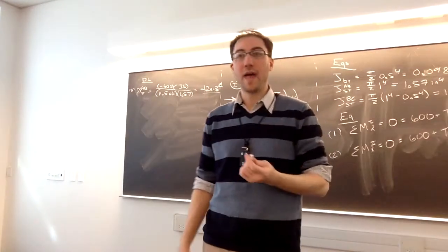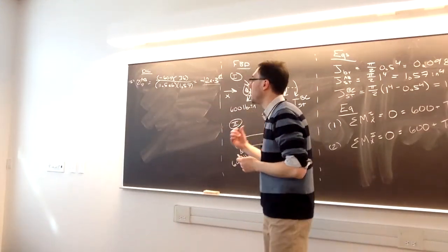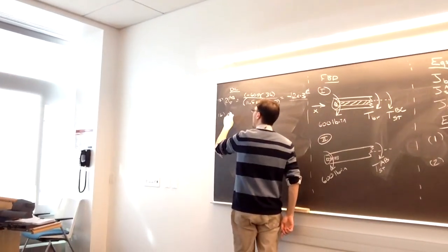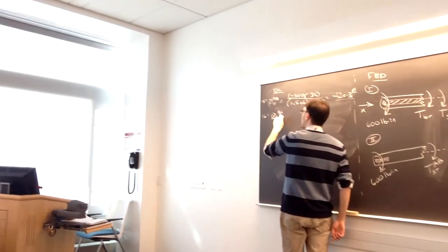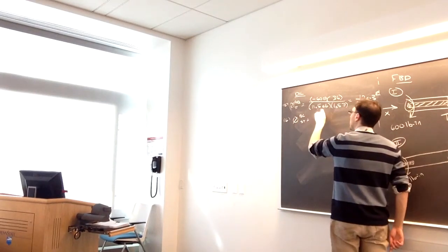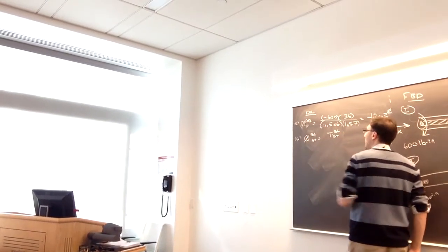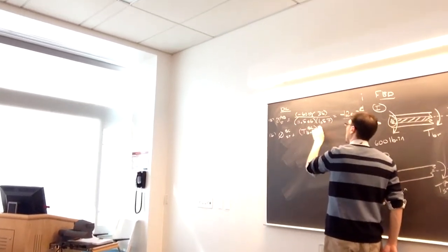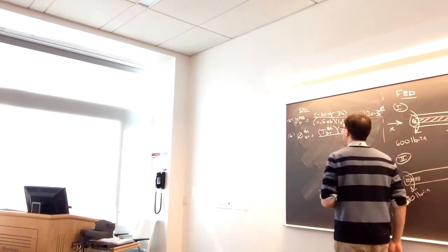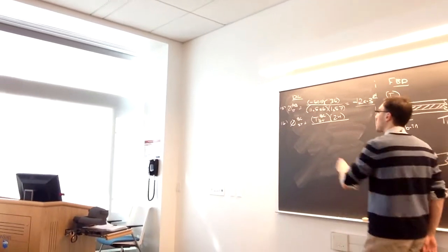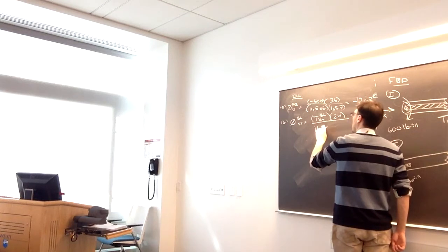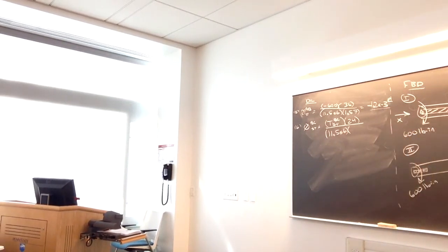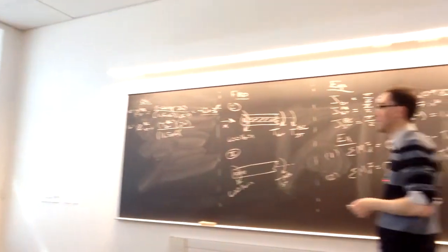All right, so we know that as a number, but now for the other step, we still have to write down the deformation in BC in the steel. We don't know as a number yet what the internal torsion is, but we know that it's 24 inches long. And in this section, the polar moment of inertia was only 1.47 because it was hollow.